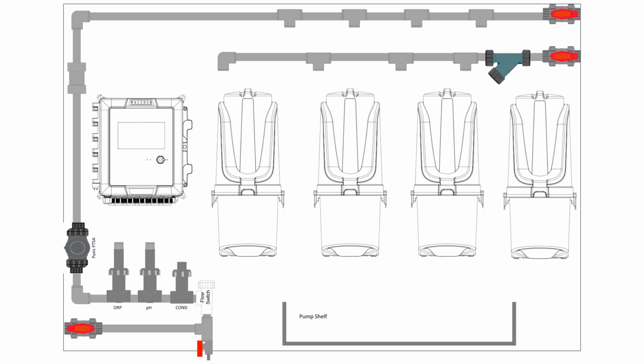Some of the old dissolvers could technically use or tolerate cooling tower water or more stressed waters. But with the design we have today and the optimization of the dissolver technology, I wanted to emphasize that the panel you're showing here is a beautiful way to set this up with the makeup water header, the inline strainer, and then the drops to the units. Yeah, I've seen some people still want to use the cooling tower for convenience. But if you want to succeed, the makeup water is the absolute right way to go.